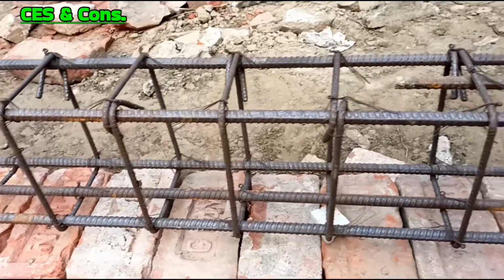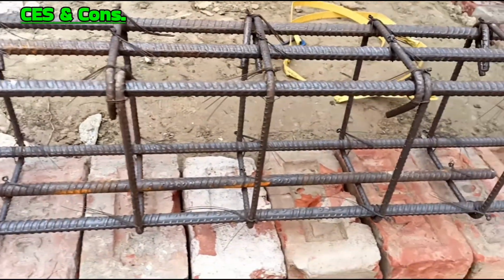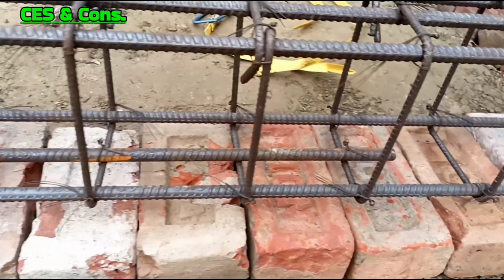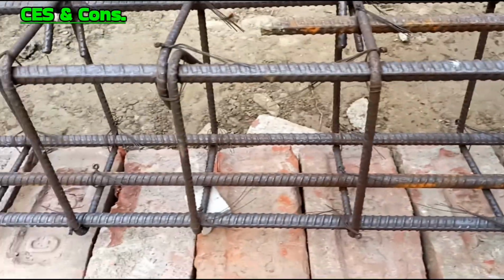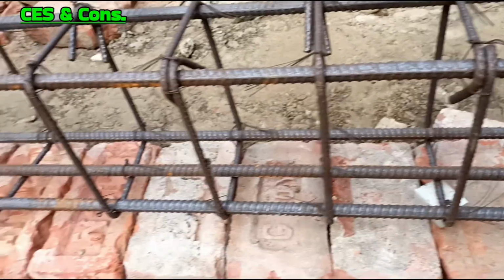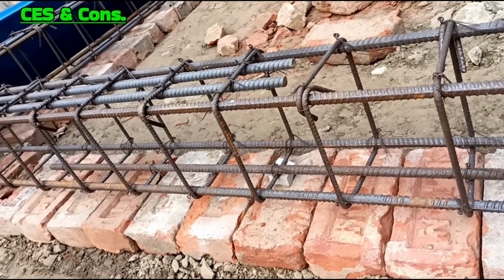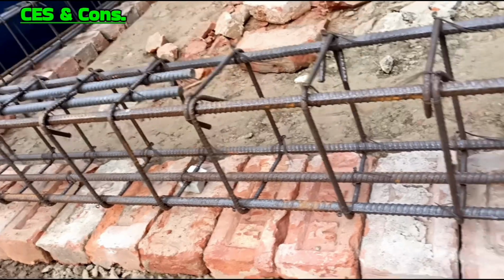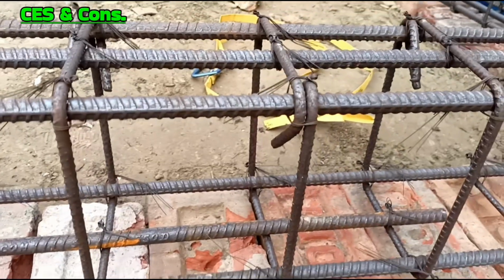Now stating about stirrups. In an RCC beam, stirrups, which are also called shear reinforcement, are critical for resisting shear force and holding the longitudinal bars in place and provide additional strength to the beam. In Indian Standard Code of Practice 456/2000, in clause number 26.5.1.6 and 26.5.1.7 and in table number 5, their specifications, spacing and design etc.